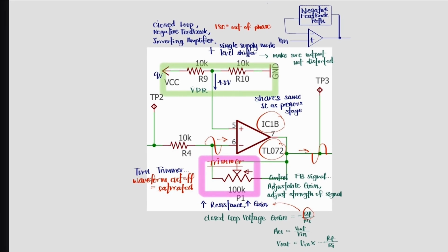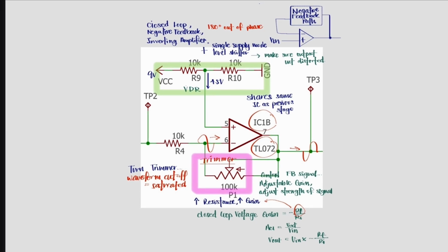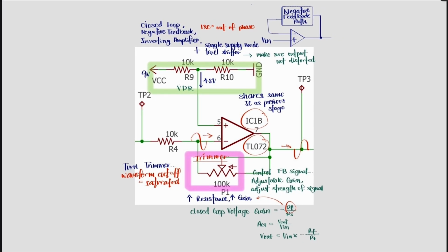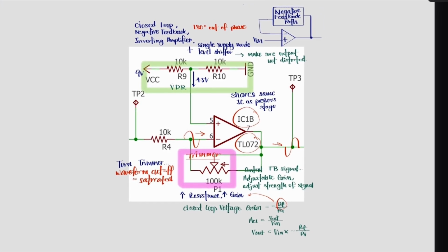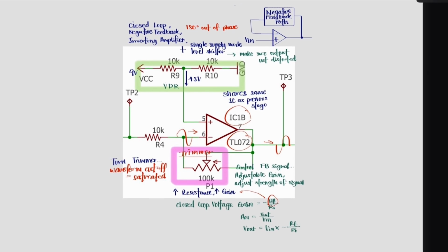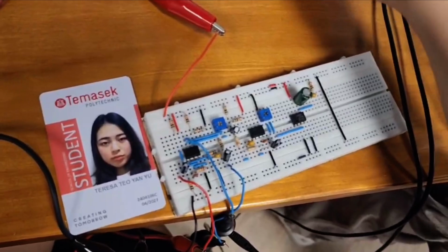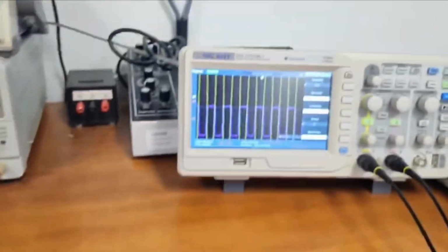In the process of stage 2, the waveform is inverted, but that has no practical effect. So further down the circuit, there is no need to invert it back. For audio output, our human ears cannot detect phase inversion and sound is still heard the same way, so it's not that important. Channel 1 probe is connected to testing point 2 and channel 2 probe is connected to testing point 3. The rest remains the same.